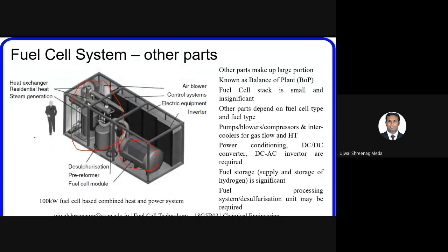The crude might have a lot of sulfur content. Sulfur is always an issue when it comes to fuel. So invariably the sulfur should be removed, or the allowable content of sulfur in fuel is very crucial and critical. If you consider the norms set by the government, such as Bharat Stage 4, Stage 6, or Euro 4, 5, or 6, every time they specify the allowable content of sulfur in fuel.